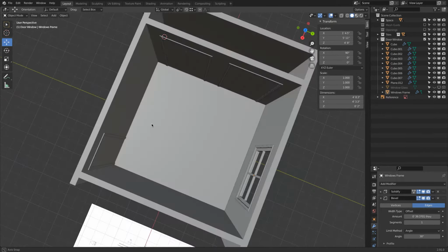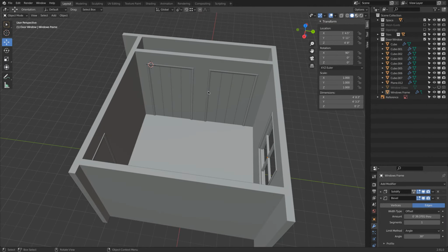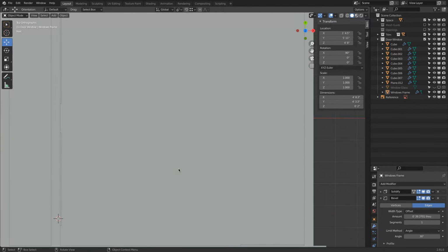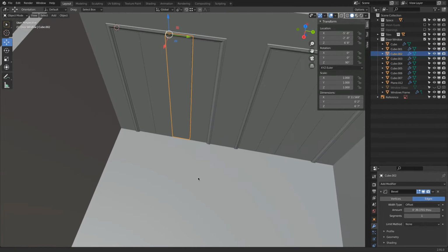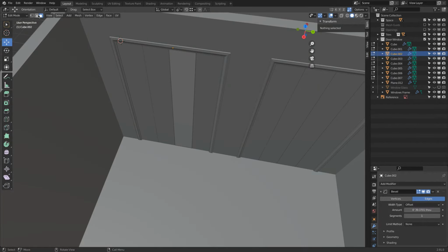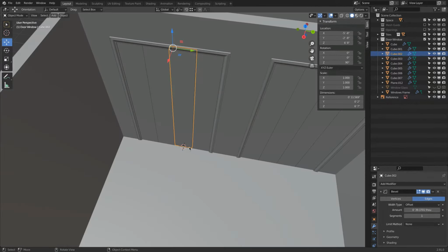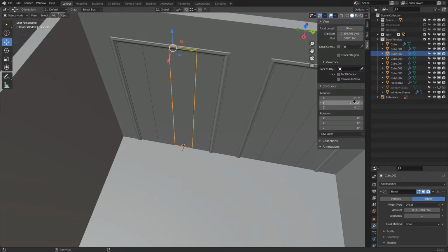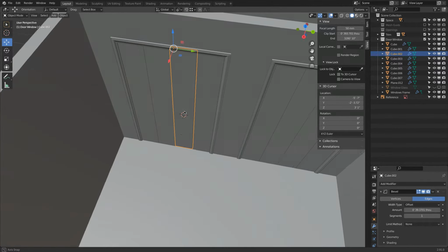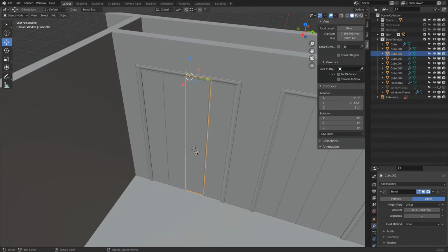So let's quickly build the door and the bifold door handles. The bifold door handles are the easiest one. Let's start with those. So we will select this object, go select this here, Shift S, cursor to the center. So this is actually centered on the bottom part. And then we want the 3D cursor, for example, we can move up plus 3 feet. Tuck. So that is actually now the center where the knob would be.